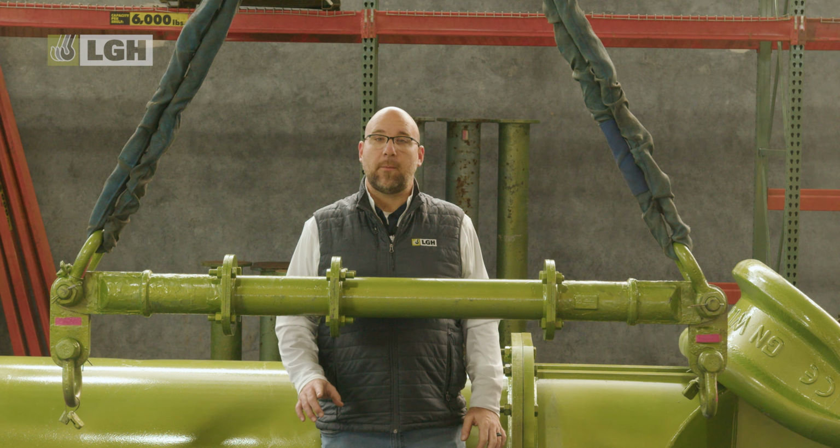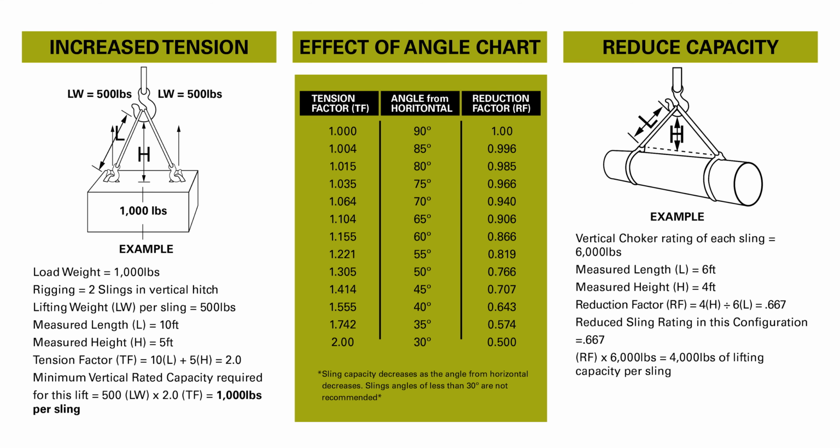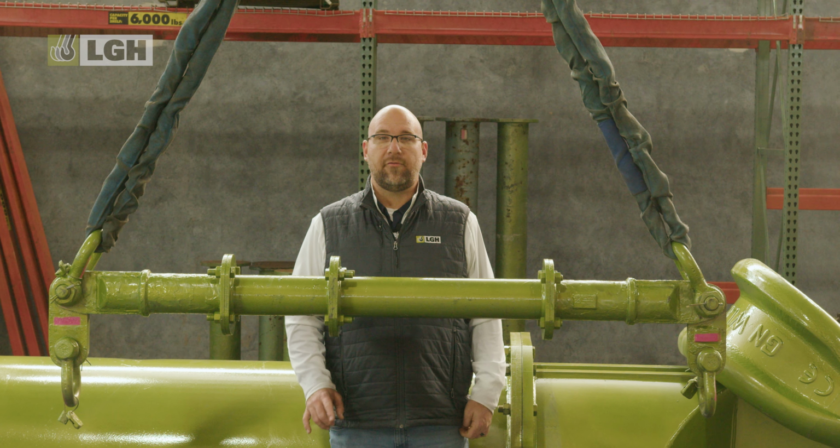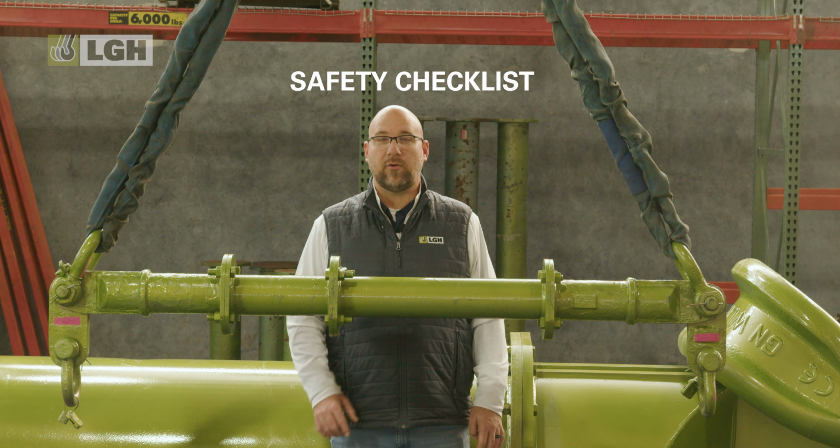To check if your sling capacity is reduced at a specific angle, determine the reduction factor, or RF, by dividing the sling height, H, by its length, L. Then multiply the RF by the sling's rated capacity to get the adjusted safe working load. Proper sling angle calculations help prevent overloads, reducing stress on shackles, lifting beams, and spreader bars, ensuring a safe and efficient lift. Finally, you can follow the safety checklist to complete before every lift.